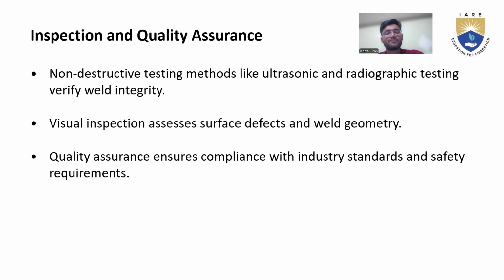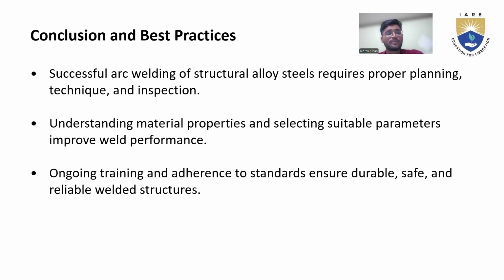Quality assurance ensures compliance with industry standards and safety requirements. While we are doing this inspection, we need to use some non-destructive testing methods like ultrasonic and radiographic testing. Those are some of the types. At the same time, defects also we need to avoid. The conclusion and best practice: successful arc welding of structural alloy steels requires proper planning, techniques and inspection.